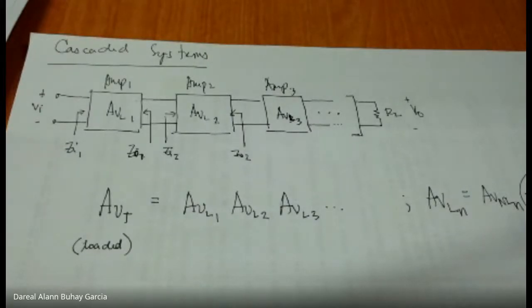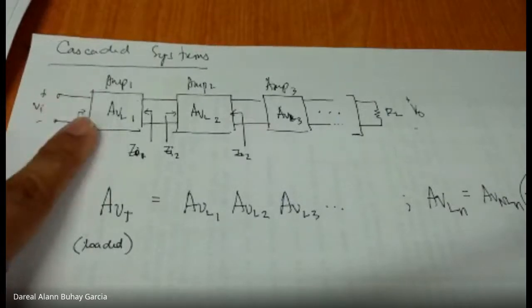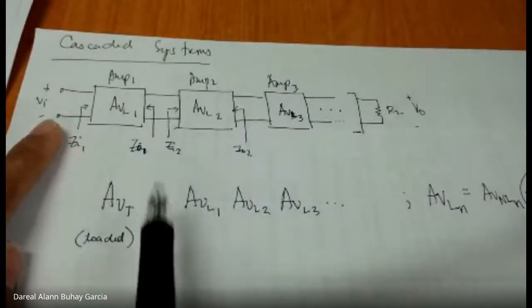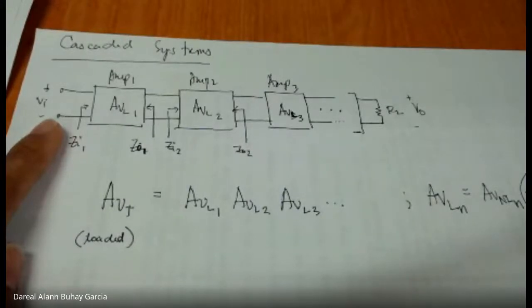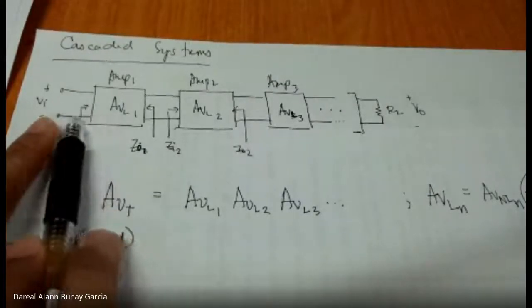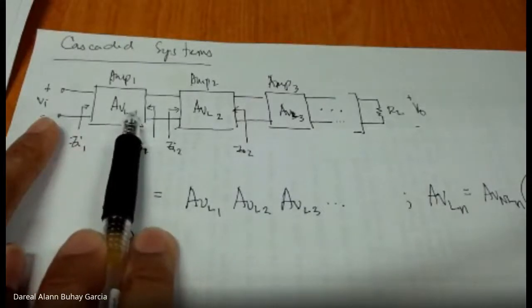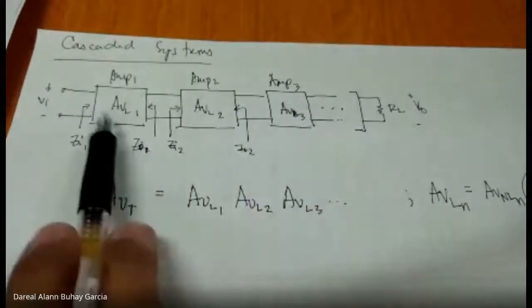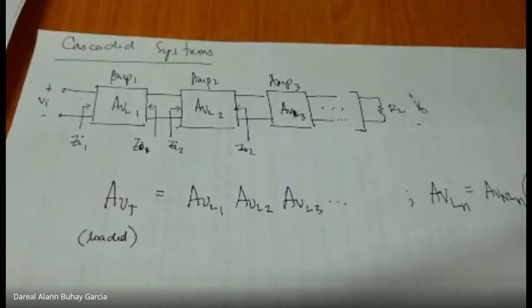Okay, it's called the low noise amplifier, because it should actually be a low noise amplifier. Good, because noise, once it enters, is very hard to remove. What we amplify also amplifies the noise. So if noise has already entered, not only the signal but also the noise will be amplified. So as much as possible, in the first stage, the noise should be eliminated, or at least minimized.